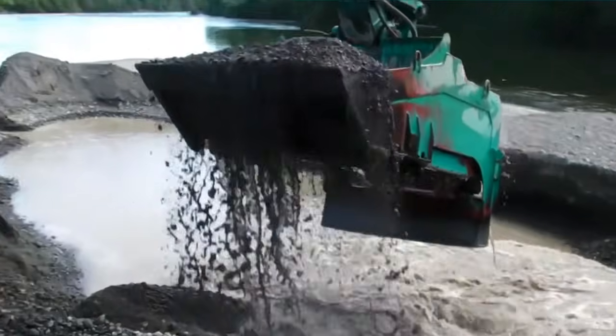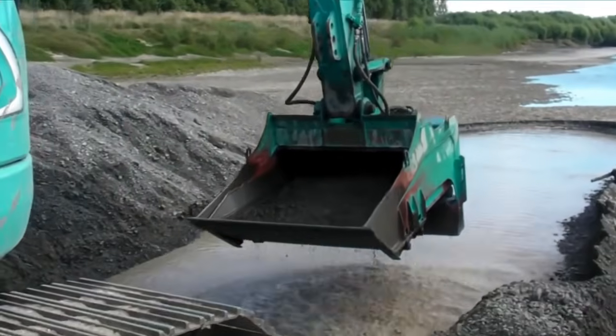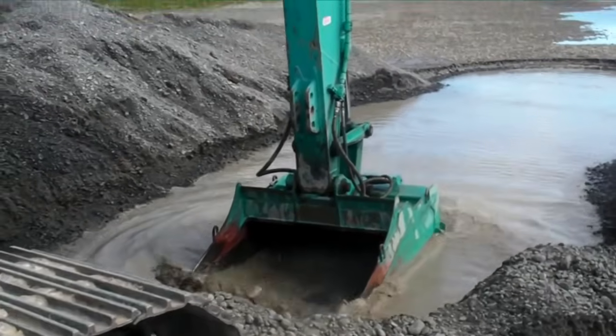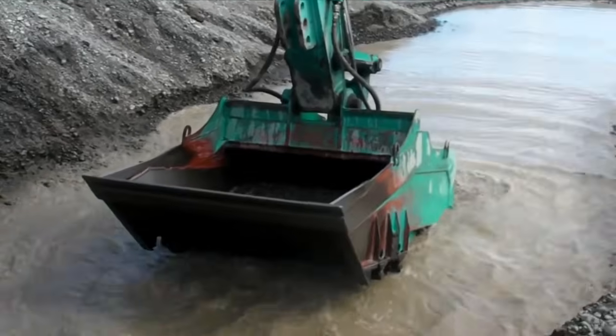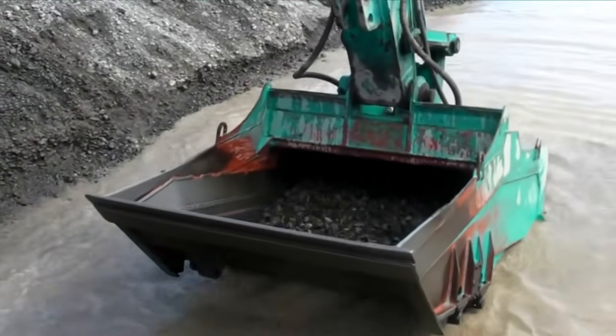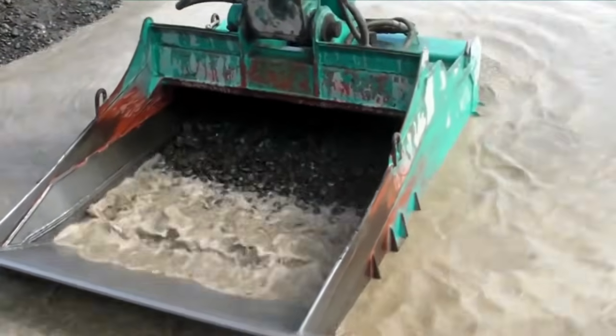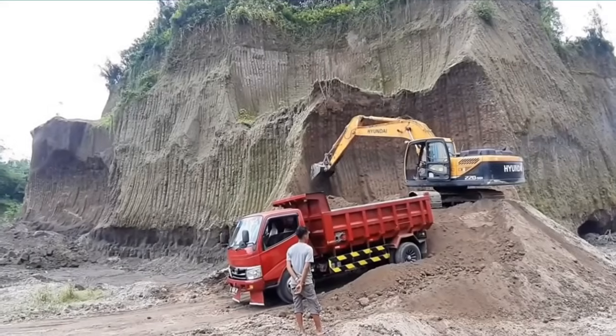Generally, these materials are available in most of the riverbeds. In some country areas, the underneath of natural ground itself has the naturally blended subbase material. The material shall be spread in uniform layers, such that the compacted thickness shall not exceed 200 to 250 mm, with due consideration to loose thickness for compaction factor.